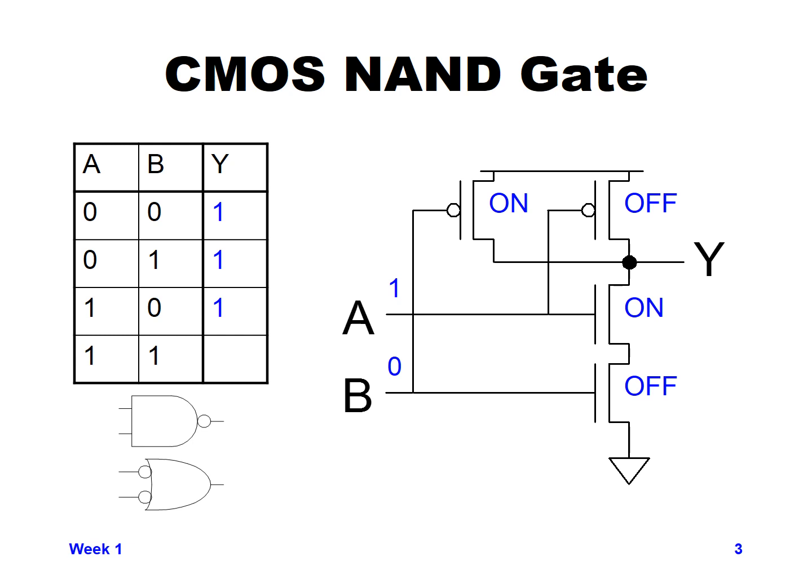Since the A input is a 1, the first NMOS device will be turned on, so you'll have a connection from Y through the first NMOS device to the second one, but the second one is turned off, so you have no connection down to ground. So you'll have a partial connection that basically gets cut off partway through. You have a connection up to VDD, no connection to ground,